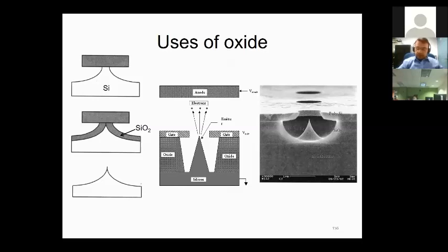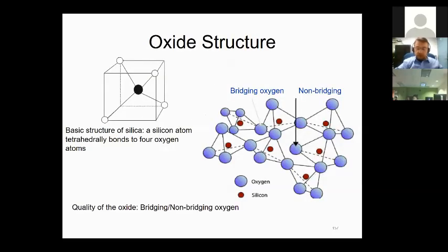All right, the thing that I want to emphasize is, since silicon dioxide is a native oxide of the silicon, it will actually consume the silicon while we're growing it. So you see, if you have this kind of a formation, and if you grow the silicon dioxide on the top, while you're growing the silicon dioxide, you're consuming the silicon underneath, so it doesn't stay at the same level. That's very critical, and we should never forget that we're consuming the silicon in the first place.